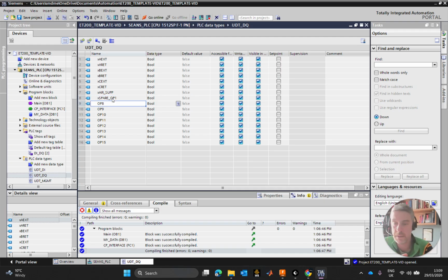Now I'm on to my second output card here, my second byte, which is byte 1 for my outputs. These are typically found on the profile plate, and found up high. What gets put up high on the outputs is usually your lights: XLGT PB1. Each button on the EduTrainer button box has a backlit coil as a light in the back, and that's what these are for. LGT PB2.